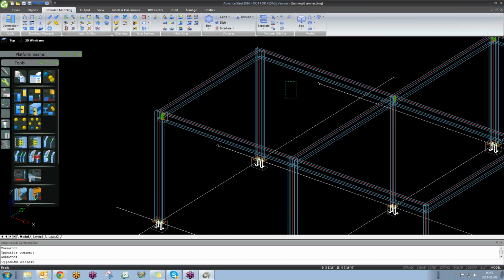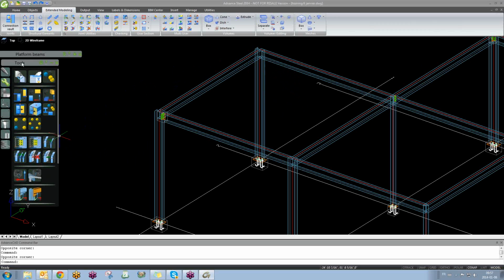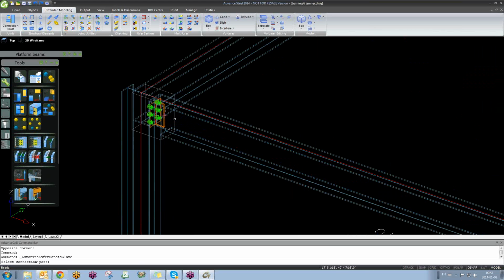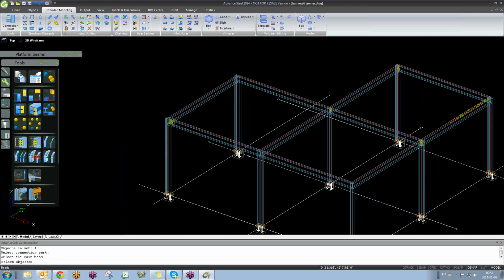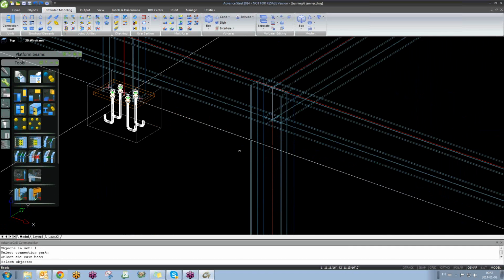So the next part will be slave master connection. As I said, under tools, do you see my screen, guys? Yes. Okay, under tools, here we have create by templates multiple. It will allow you to create some connections, but without any control between them. But here, create joint in a joint group. This is the slave master connection. So when I click here, I have to select the master one, the reference. When I click, enter. Now I have to select to reproduce the connection. Just select this one, enter, this one, enter. So I will have the same connection.